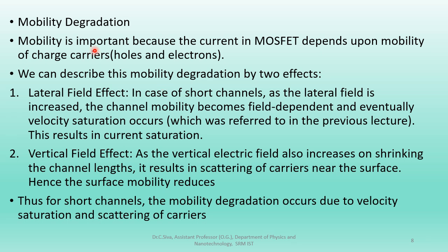Mobility degradation. Mobility is an important factor in the device, because it determines how fast the device can be. Current in a MOSFET depends on carrier mobility. In short channels, mobility gets reduced due to two mechanisms: one is the lateral field effect and another is the vertical field effect.